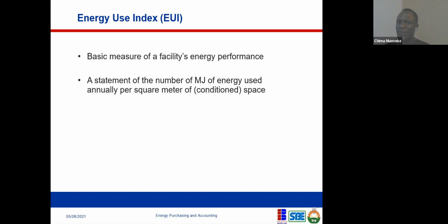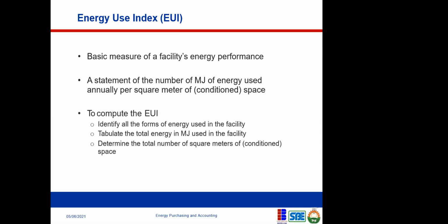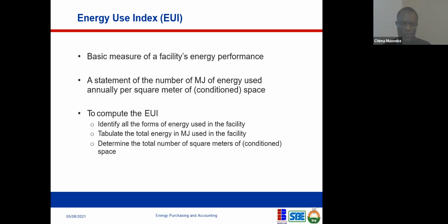I want you to understand the concept of energy use index. Is that clear? Not quite, so maybe along the line it becomes clearer. To compute the energy use index, you have to identify all the forms of energy that are used in that facility. You tabulate the total energy in megajoule used in the facility. Then you determine the total number of square meters of conditioned space.